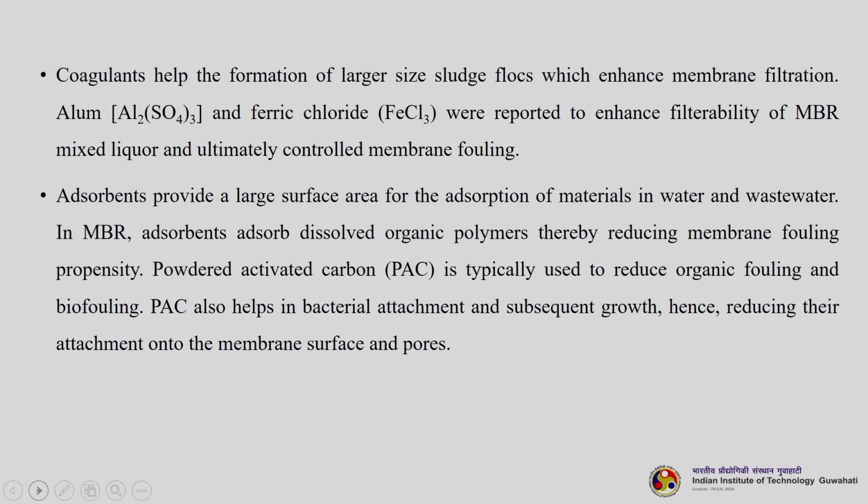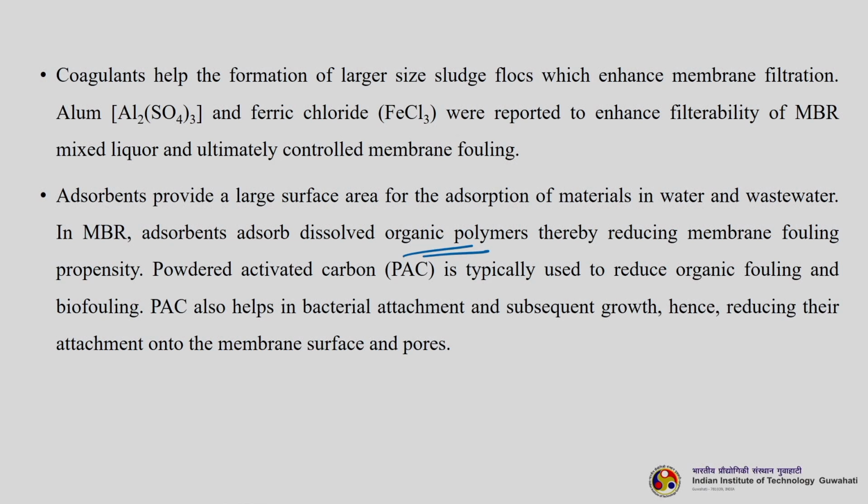And then you can add adsorbents also. They have a very large surface area for the adsorption of materials in water and wastewater. What they adsorb depends upon the charge based interaction of the component that wants to be adsorbed on the surface of the adsorbents. So, basically they are adsorbing dissolved organic polymers, thereby reducing membrane fouling propensity.